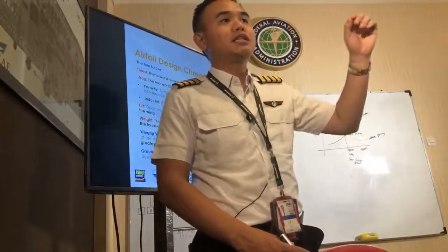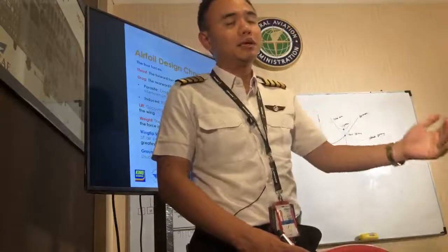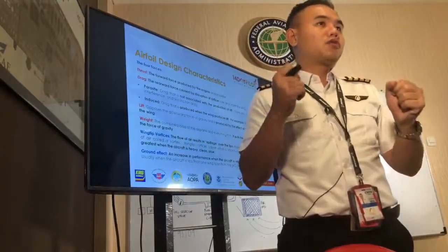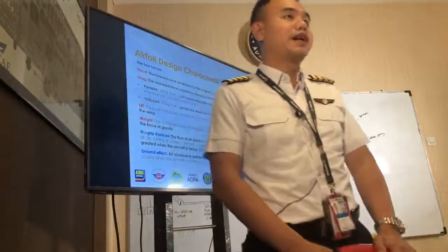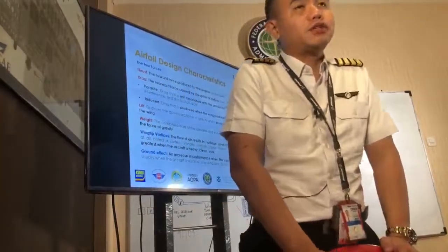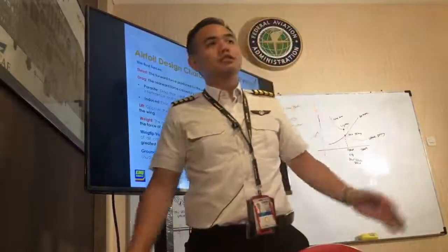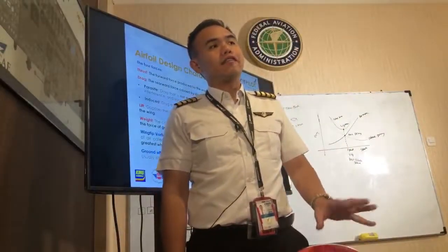That's why, if you have engine failure, there's the ABC checklist, ABCD checklist. The A is: you have engine failure, pitch for the Vg. The Cessna is 65, the PA-28 is 73. In the Duchess, every airplane is different.